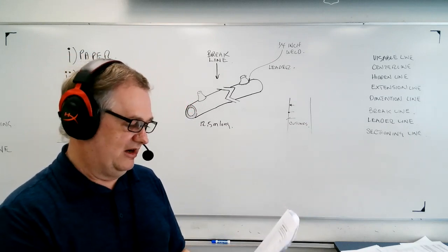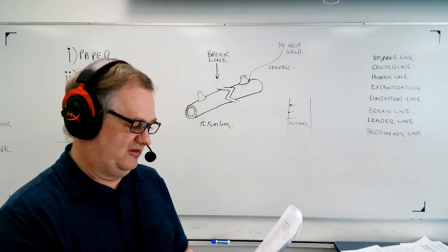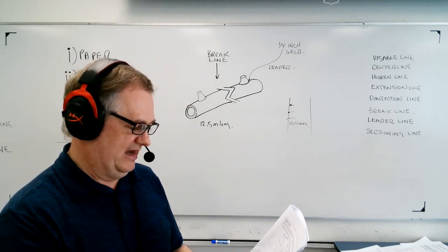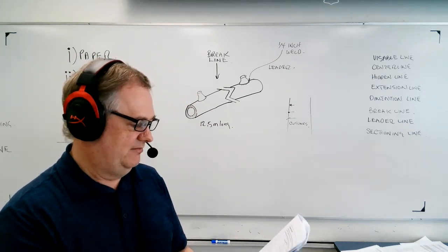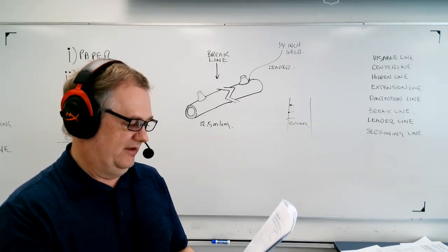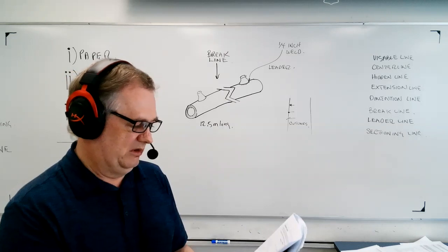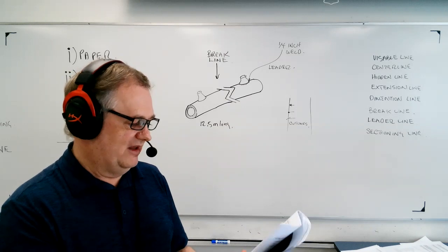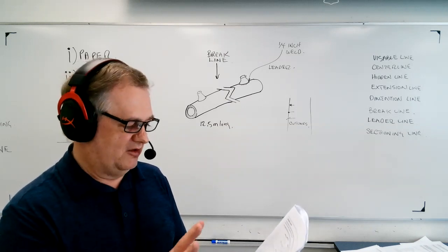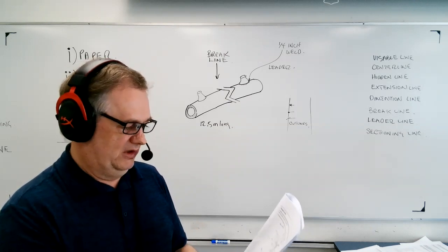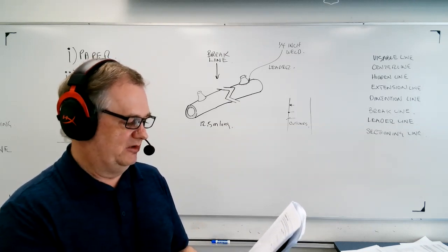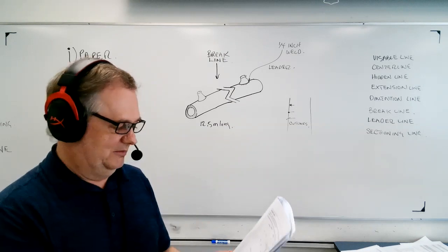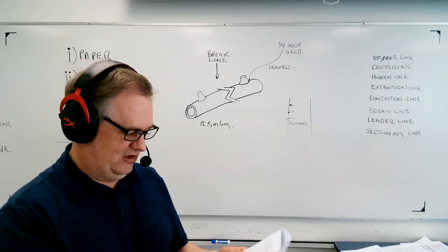But if you look at that, you're going to see, starting at the top, they have dimension lines, extension lines, leader lines, sectioning line, break line, hidden line, center line, and the object line is what we would actually call a visible line, where it says object line. It's a visible line that shows that thing. There is another type of line if you want to superimpose or show another piece of equipment in close proximity, and it's very similar to a center line, but it's a longer line and then 2 dashes. They call that a phantom line. Doesn't come up all the time, but you can see it's in there. That's nice to know as well.